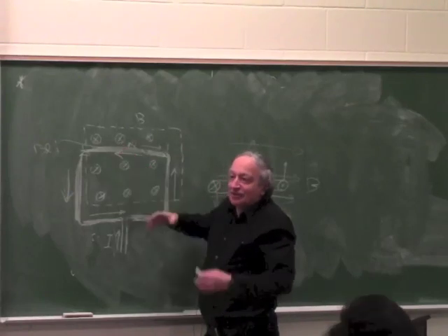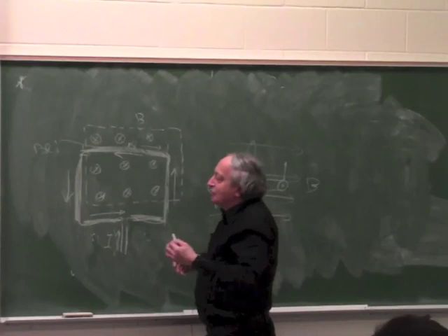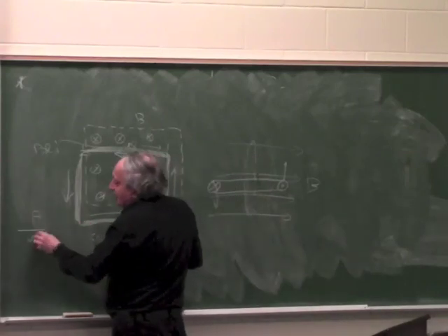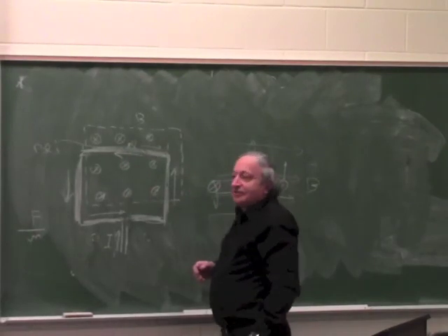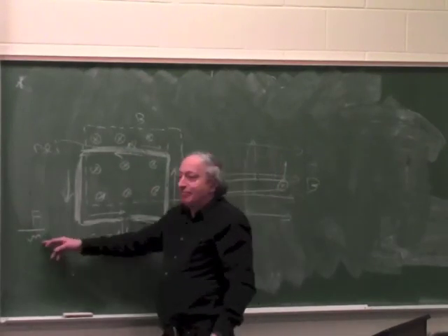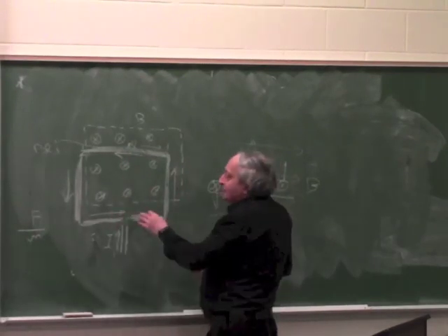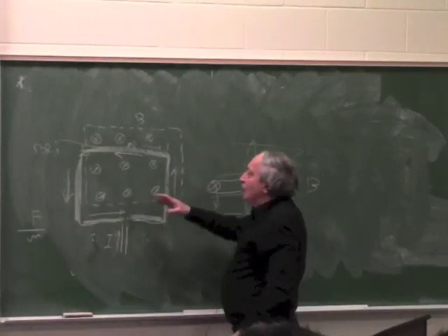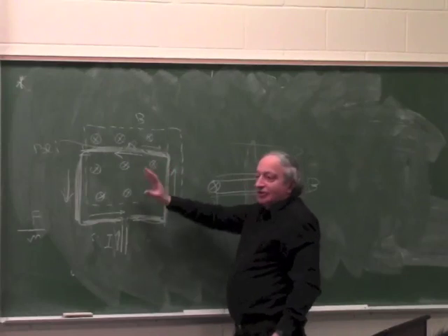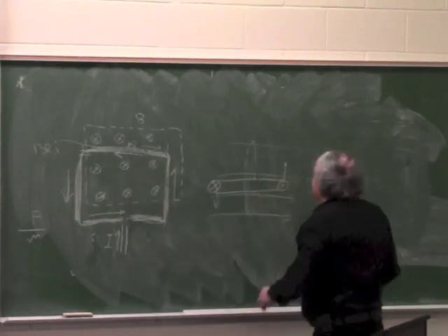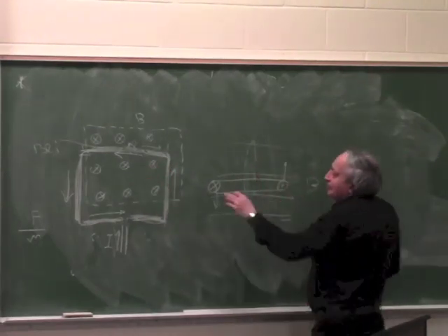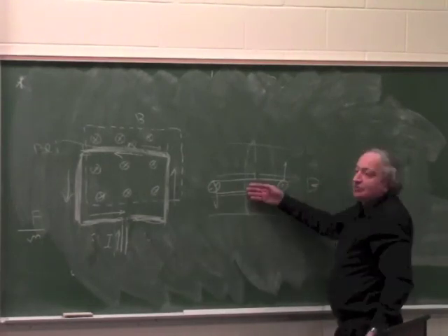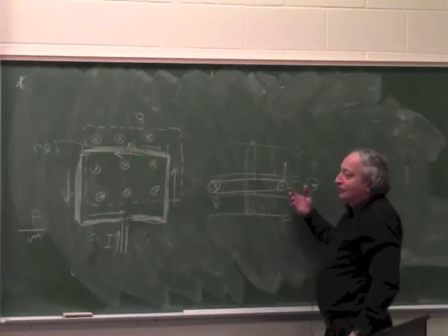Okay? So if you think of the efficiency of the actuator, which is the force over the weight, the M is a mass. So this has 4 masses, but only 1 force. Now, if you want to make a coil which generates a torque, the situation is a little bit better, because in this coil, which is wound this way, 2 of the arms generate torque and the other 2 do nothing, but at least 2 of the 4.